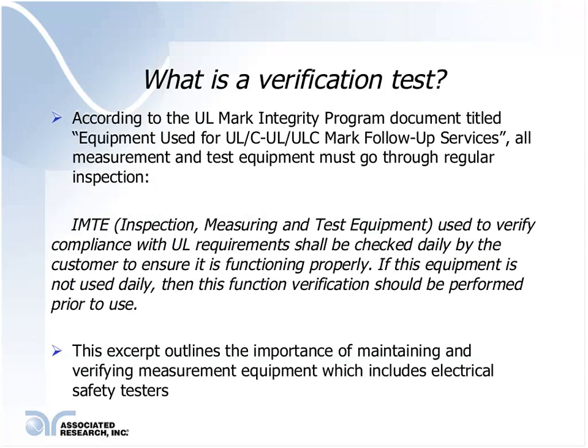According to UL, they have a document which outlines the importance of maintaining and verifying measurement equipment, which includes, of course, electrical safety testers. And this is a direct excerpt from the UL document, which says that inspection and measuring and test equipment used to verify compliance with UL requirements shall be checked daily by the customer to ensure it is functioning properly.